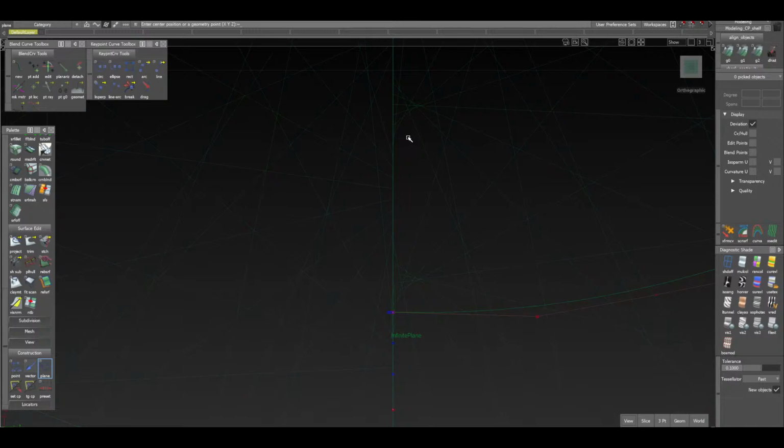So what I'm going to do is I want to introduce you guys to, so in Alias we have the general world, or the default world, okay? And the default world is linked to the view cube, which is over here, okay? And it works pretty good for most of our needs, okay? But when we're working with construction planes, things can get a little bit weird, okay? And it's got to be that way because when we're working with custom construction planes, everything becomes relative. Our viewpoint, our perspective becomes relative to that construction plane that we set, okay? So once we've established a construction plane like we've just done over here, we want to work with it, and we want to associate ourselves with it.